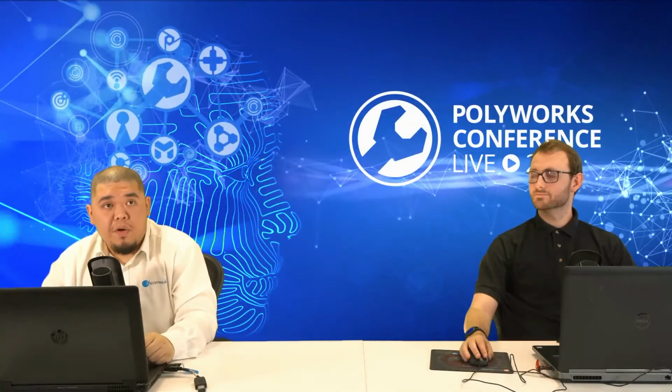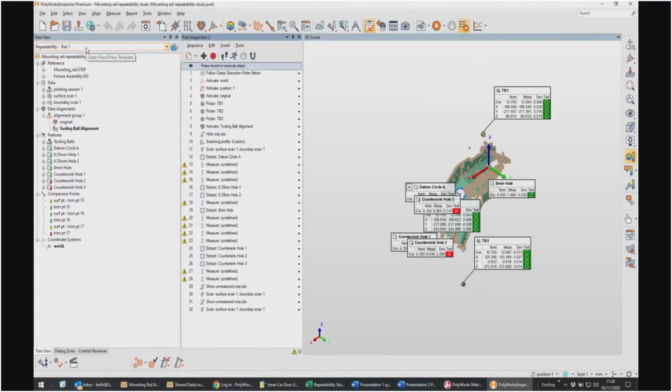So I've got word from the quality team that all 10 measurements are completed and have been uploaded to Data Loop. So I've logged in and downloaded the project. I can see that all 10 pieces are in the project. So now I'm ready for the repeatability study. I'm going to use the Excel spreadsheet provided by Polyworks to calculate variability.